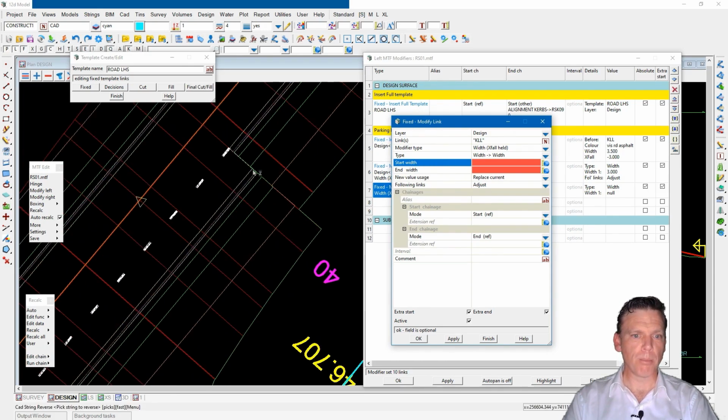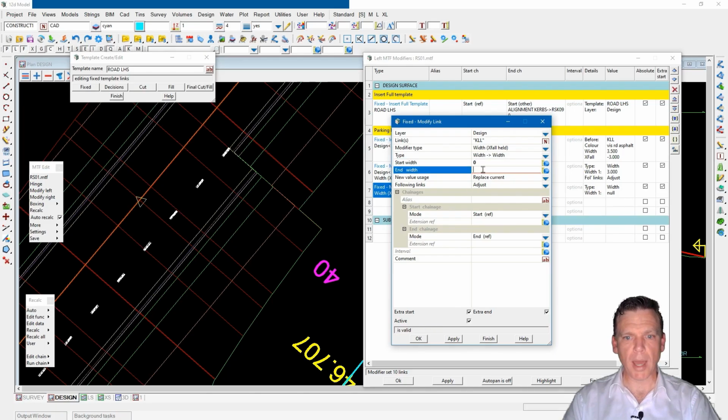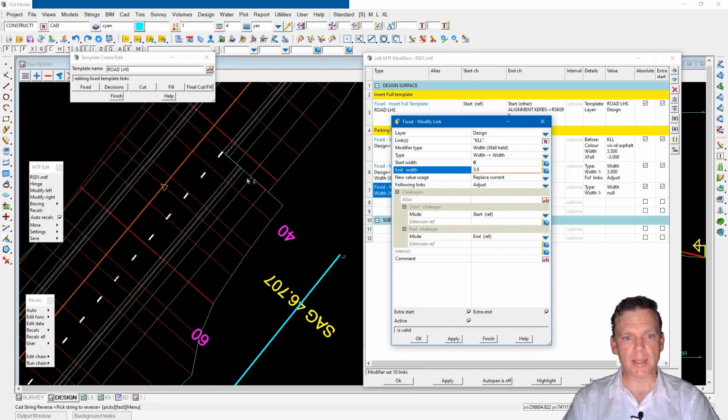And essentially I want to bring this yellow string in, or the lip of the curve across, so that there's no width at that point. But as I come down to form this triangle shape up, I actually do want to have a width of 3.0 meters. Where's this going to take place? Well, I've already utilized the aliases before, so let me do that again.